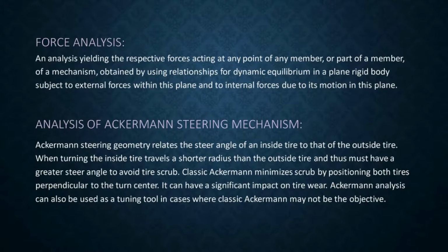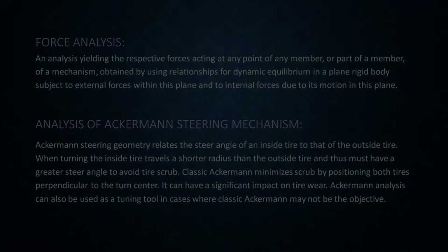Classic Ackermann minimizes scrub by positioning both tires perpendicular to the center. It can have a significant impact on tire wear. Ackermann analysis can also be used as a tuning tool in cases where classic Ackermann may not be the objective.